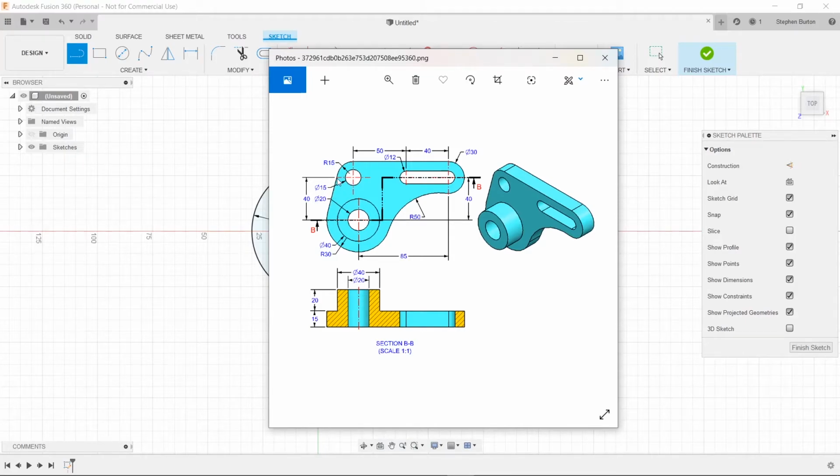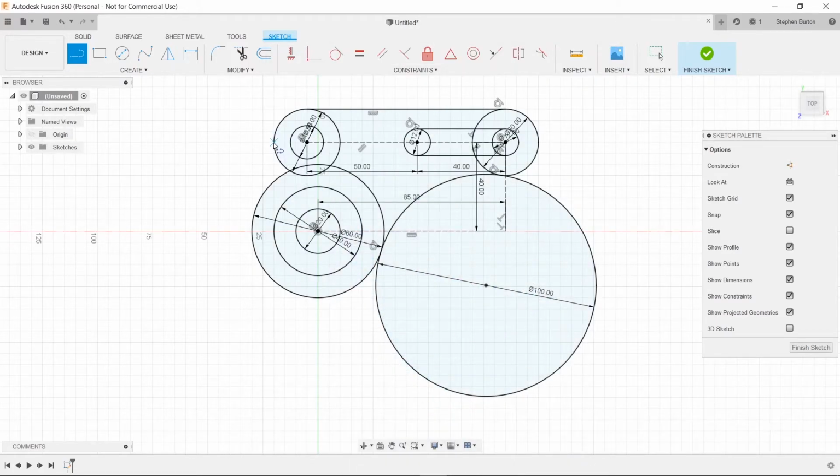This circle or this line right here, it has to be tangent to both of these as well. But if we look at it here and we do this, it's not going to be nice and straight. You see how it dips down like that? It's just going to look ugly. So we draw it, and then we're actually going to Control Z that. We're going to draw it one more time, but not make it snap to anything. We're just going to kind of draw it there.